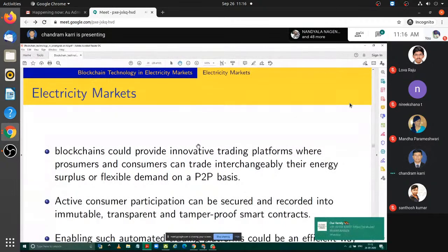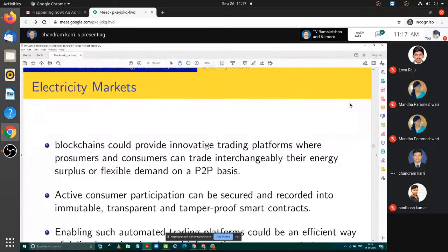In India, in the decentralized power market or restructured power market, we are doing the transaction in a bidding process. The supplier will bid for some amount, and buyers will quote some amount. At present, the independent system operator will match both. The bidding process happens at the level of the independent system operator by looking at other constraints like transmission. When it is transmitted, its capacity should be checked, along with some contingency analysis. It's complex, so we require some kind of technology to run the power markets in a smooth manner.